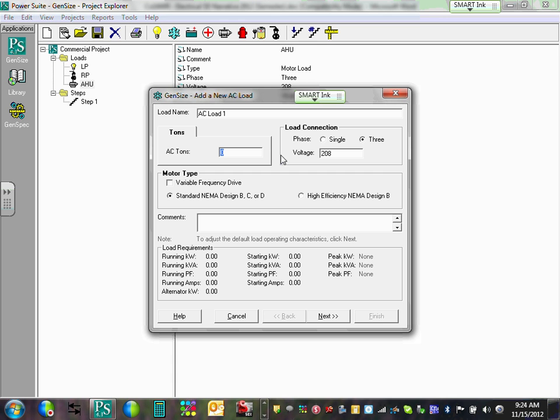Now, here's how we handle it. Can you guys see the running amps? Let's put 10 tons, and you look at the amps at the bottom. Everybody can see the amps. How many amps does 10 tons give you? 52. How many amps are we looking for? So how about if we put 15? That's how I kind of manipulate it. No, 50. Not close. Let's say 16.